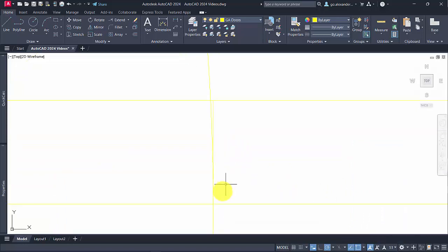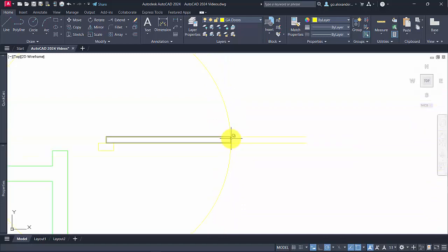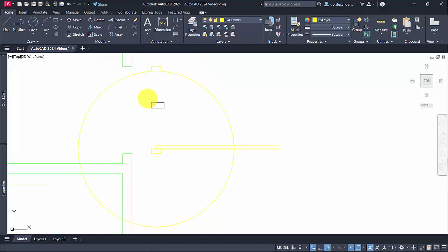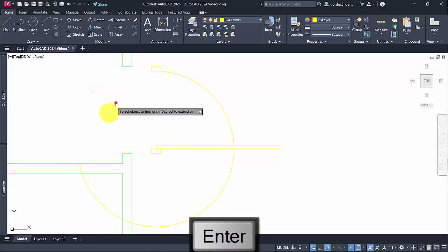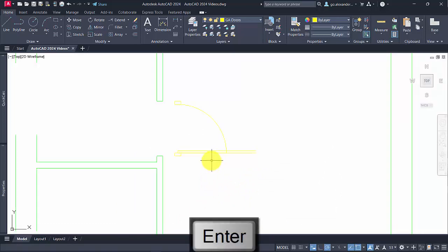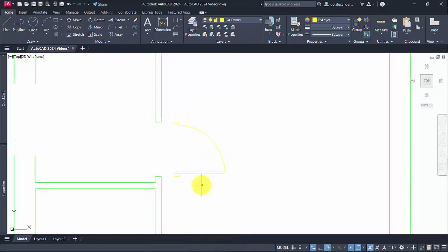The reason why it's important to choose that line as the second point is the door is a little bit thicker than it would be just at that point. I know it's only a matter of millimeters, but let's draw things as accurately as we can. We'll use the trim tool then at this point to trim out the parts of the swing that we don't need. I guess drawing it in the plan itself has interfered slightly, but it's good to have it close to the door opening so we can see that it's accurate.